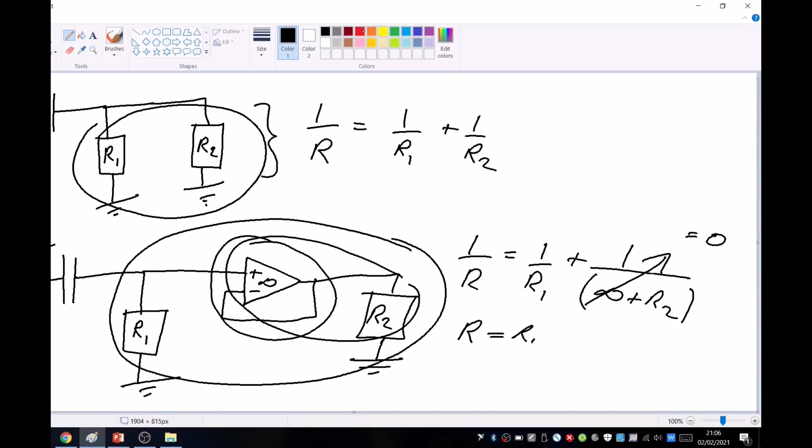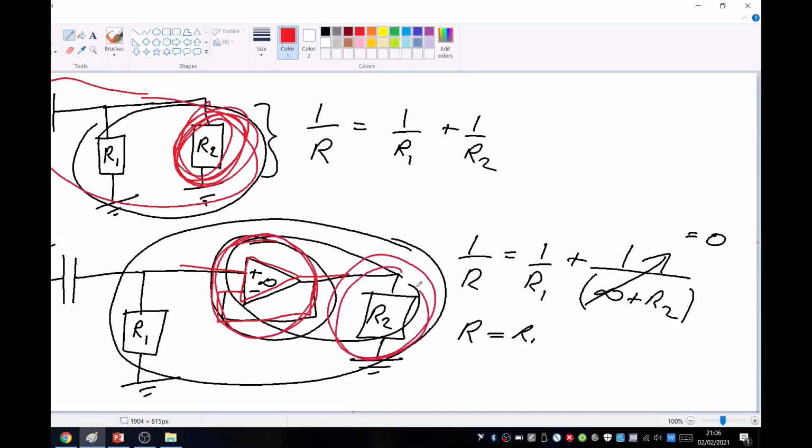And if you remember from yesterday, this circuit here is our voltage follower. So it's a non-inverting amplifier arrangement with unity gain, and it was to isolate different parts of a circuit. So in this first case, our additional resistor has affected our circuit. However, because we've used this voltage follower to isolate circuits, then by adding a resistor, we haven't affected our filter. So that's one application of where a voltage follower might come in.